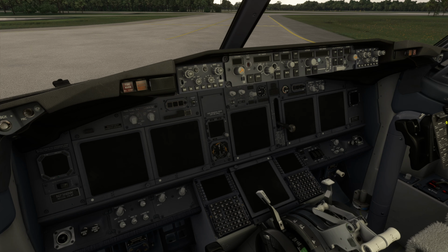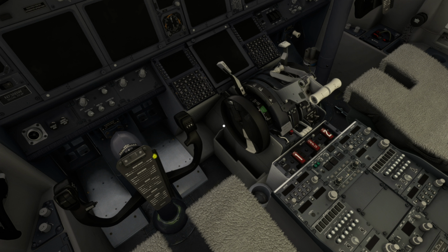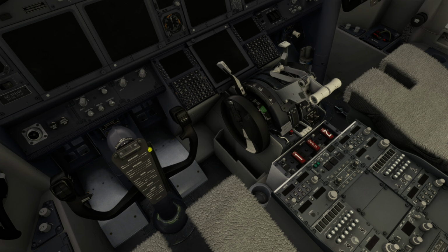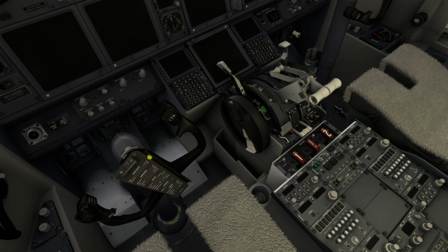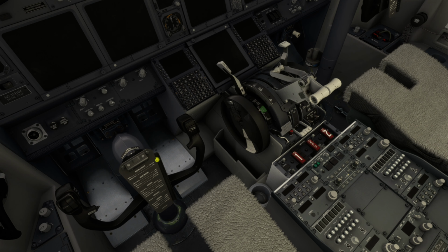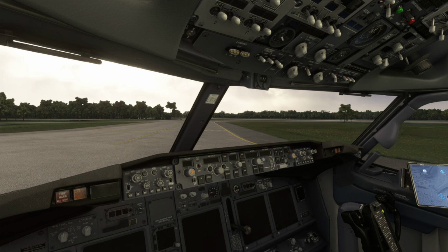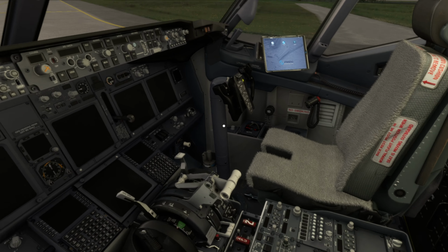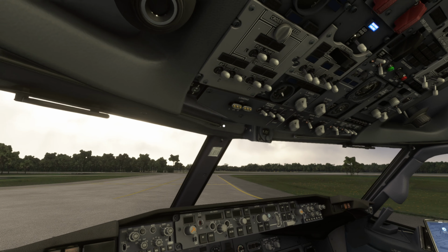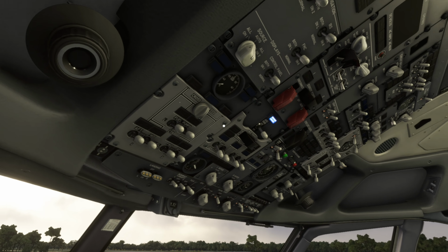This means that we've got ourselves no capability to control this airplane beyond the cable mechanical control surfaces that are active on this airplane, with no hydraulic booster pumps or anything like that. So flight control would be very, very slow and sluggish to respond, and it would require a great deal of physical effort from the crew in the pilot and first officer seats here. However, to rectify that situation, we've got ourselves the ability to bring electrical power into the airplane.